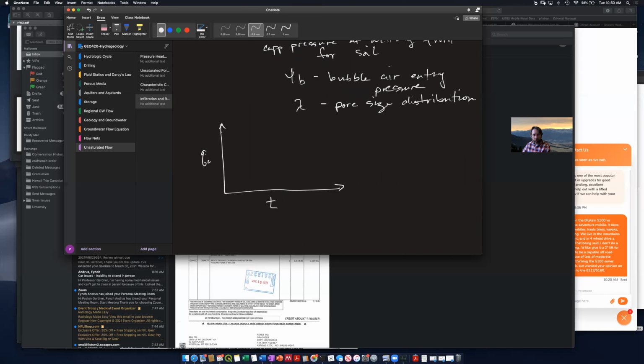And we'll get this infiltration rate. It's going to start off really high, and it's going to converge to a steady state. This is the beginning of the precipitation event, and this is sometime after the precipitation event begins. All right, so that should be good to go. And that's how we calculate infiltration rate.